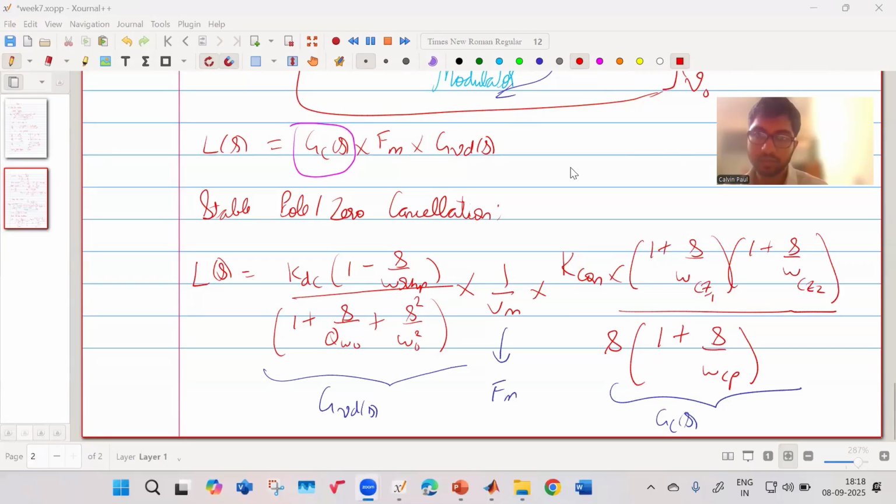Sir, you're considering this for the ideal converter only, right? Yeah, for the ideal converter, you're considering. Okay, fine. If we include DCR, ESR as well, this expression of Q and omega naught only will change, whereas the form remains the same. So this analysis is also valid when there is a DCR, etc. When ESR is added, there comes an additional zero that I've not shown here, but that we also can see. So first I'm doing the ideal case so that it becomes simple.